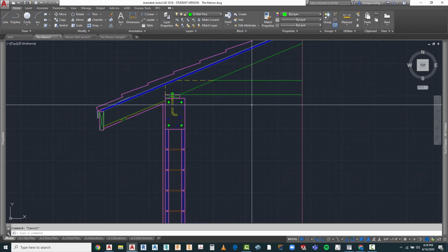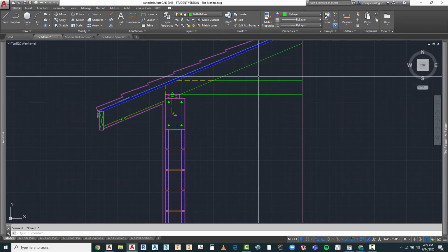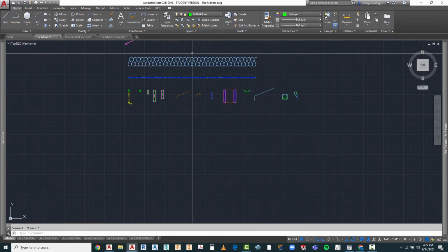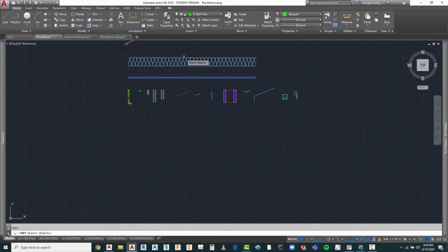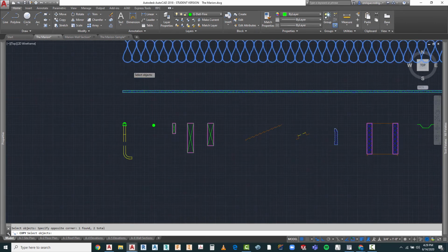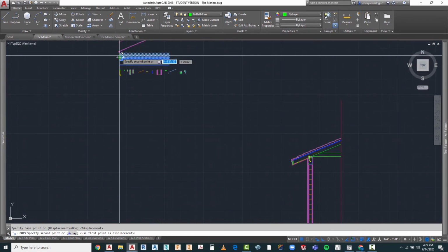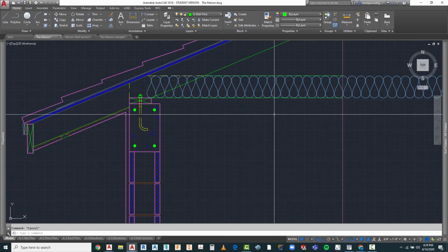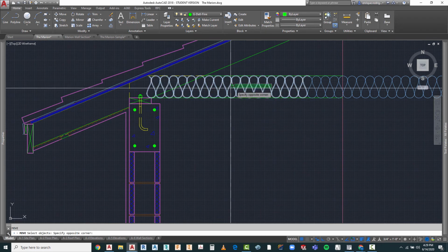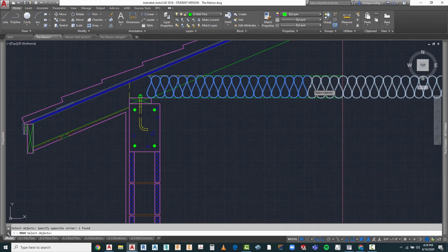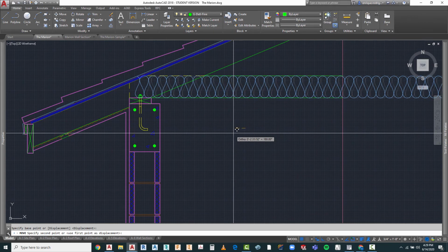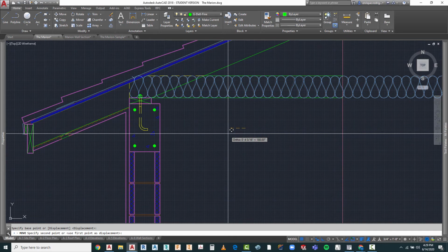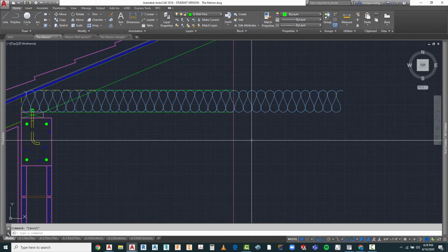Let's go ahead and bring in our insulation. So let's take this element, and I'm going to copy it. This is what we call batt insulation, and a number of things vary in terms of how much heat resistance it actually provides. You have R19, R30, etc. So I'm going to bring this all the way over to here, and I'm going to trim this out here.